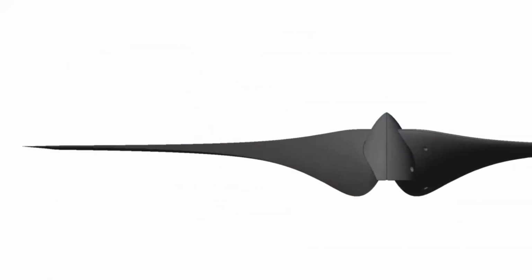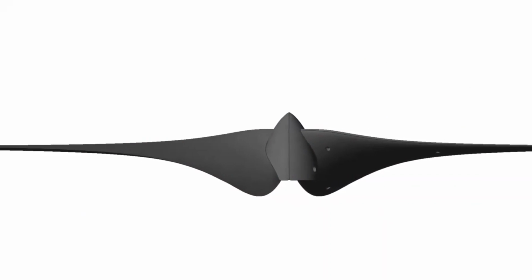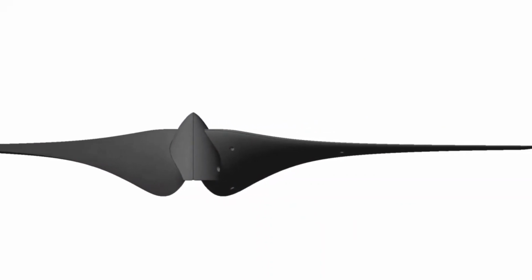Upon reflection of our design process, we noted that we did not conduct sufficient analysis of the aerodynamics of the root. This is because we created a large surface at the root, causing an increased amount of drag while producing the same lift, leading to a loss of power. This could explain our low CP value.